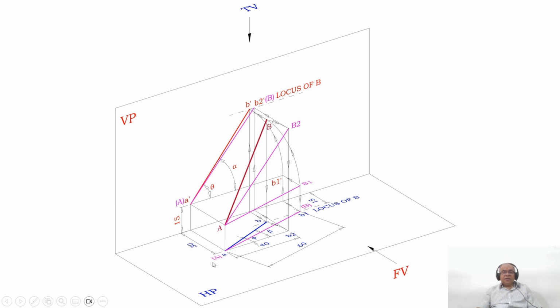How to obtain that? Here, as we rotate it in space, what happens to the image? That line which was there from here to here has been rotated till here, where you have AB2, the line which is parallel to XY. Once you get this point, then looking from the front view, this B2 projector will fall on the locus of B in the front view. So you mark that point as B2 dash and join A dash and B2 dash with a line a little thicker than the XY line, and you mark this as capital A and this as capital B.